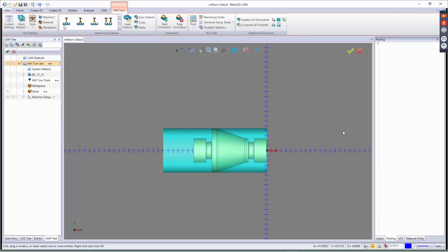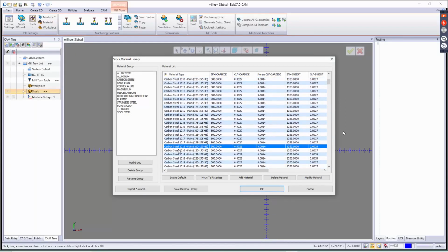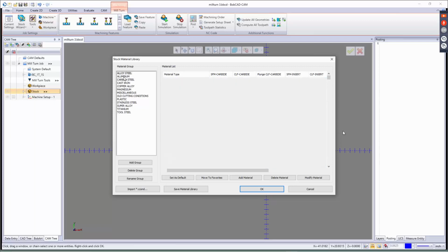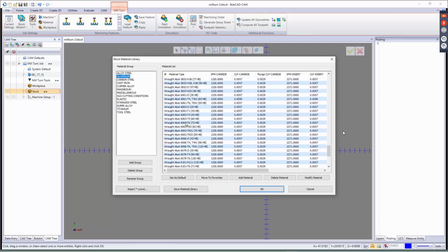Next over is our job settings. So you can set up a different machine if you don't want to use a BC2X mill, or excuse me, BC1 turret, one spindle. You can choose a different machine. And when you change the machine, the post will also change. You can also change the material if you want. Like I said, by default, it is carbon steel that we set up, but you can go to, let's say, aluminum here, and